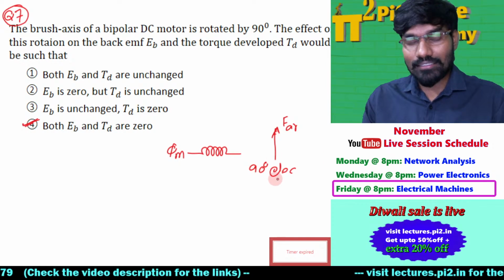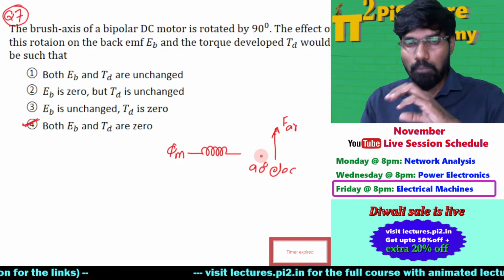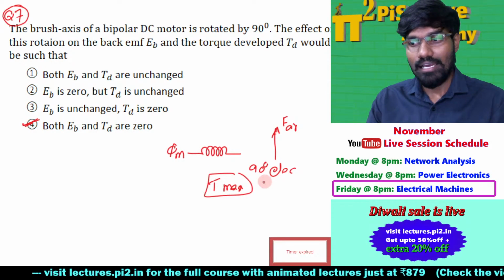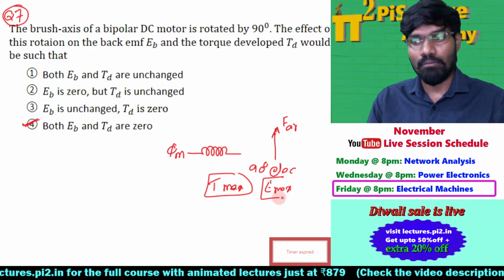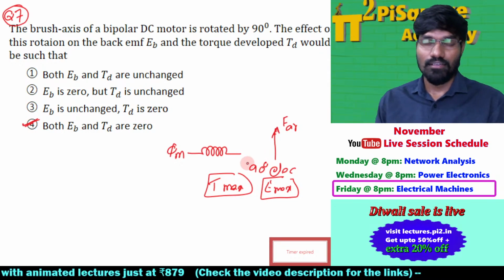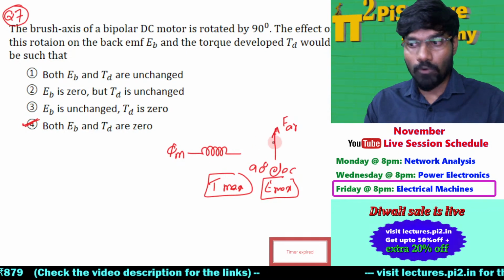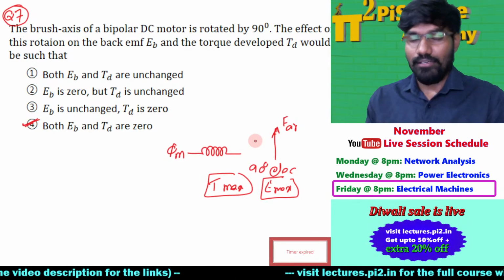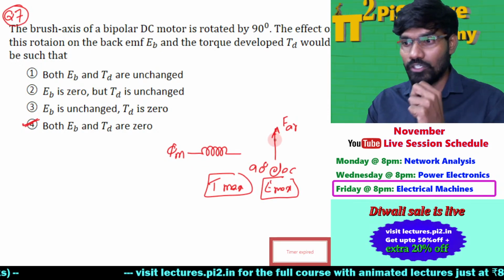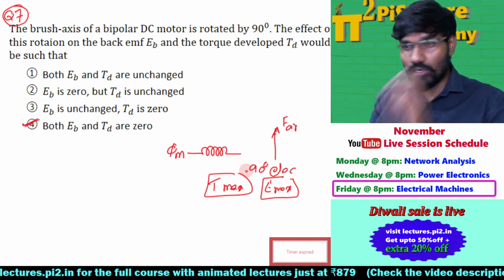When you have this electrical angle of 90 degrees between these two fluxes, the torque is maximum, you will get the maximum possible torque, and you will also get the maximum possible EMF when it is exactly 90 degrees. And the second advantage which only the DC machine has is that both are decoupled, independent of each other. I can control phi m independently, and I can control IA independently. That is another great advantage.